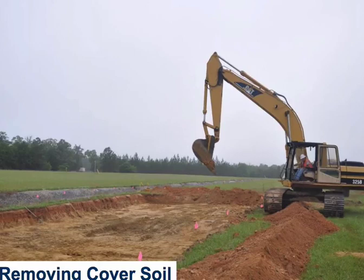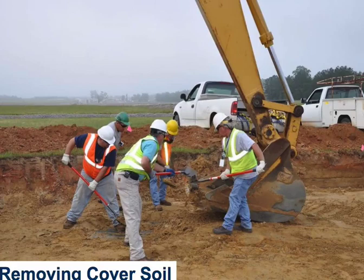So this process is pretty fun for those of us in academics, get out into the field and get our hands dirty. Here you see removing cover soil. This is from an LLW facility. Excavator help. You need to be careful not to puncture the geosynthetics, and so the excavator is only a little bit of help. It gets off the top layer. After that, we need to do it by hand.